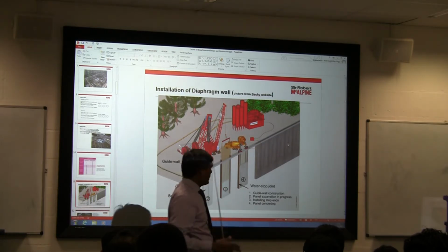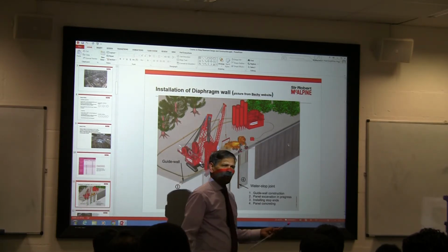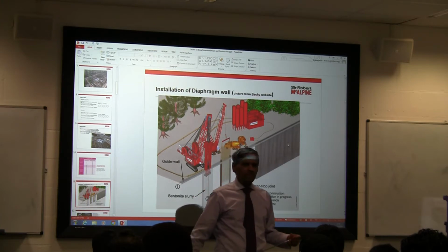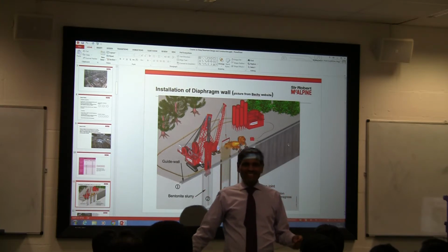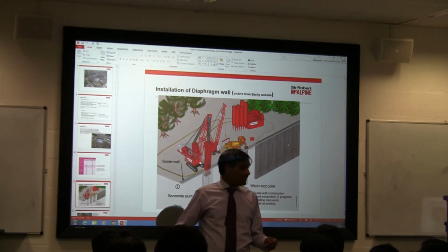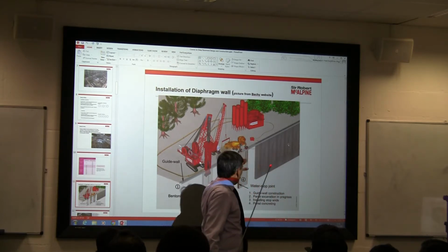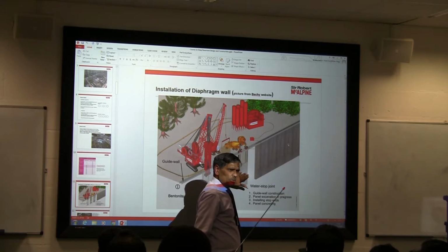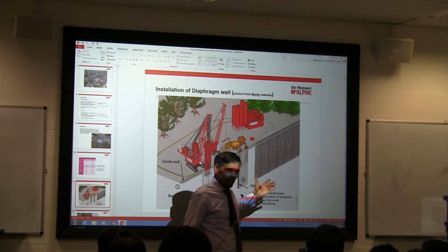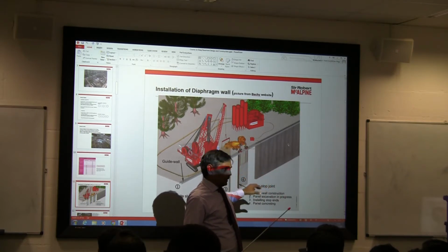How do I fix the reinforcement? Why do I have to put the reinforcement? What happens if I don't put the reinforcement? Yeah. So it's a plain concrete. You're going to dig next door. So the plain concrete wall, it won't span. It's simple. So the concrete will not span.